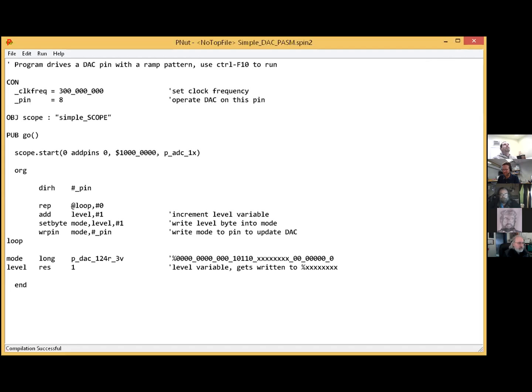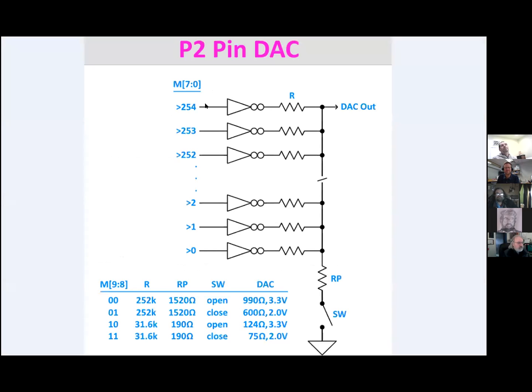I was wondering, are the DACs pulse width modulation DACs? No, I'll show you real quick here. They're very simple. It's just a resistor summing system. We have some thermometer logic. We have 255 of these things, and they just drive high and low and sum together. Then there's some thermometer logic that determines how many are low and how many are high.